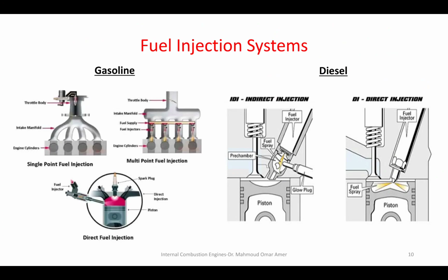So when this jet enters the pre-chamber, it starts to swirl. Okay? When the swirl is happening, the injection starts. So the fuel is injected inside the pre-chamber. Due to the high compression ratio, the air inside the pre-chamber is very hot. Okay? So when the fuel is injected, it ignites. So the pressure inside the pre-chamber increases. So what happens to the flow? It reverses its direction. Now the higher pressure is inside the pre-chamber.